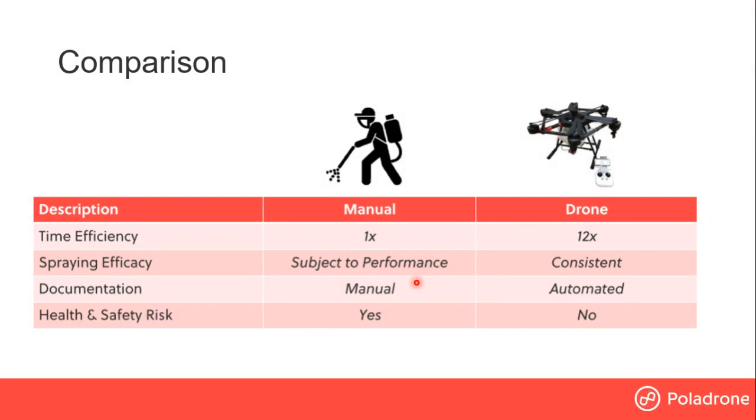Yeah, sure. But logically speaking, if we do spraying manually, of course in one day we can cover 1 to 2 hectares, depending on the environment also. But in terms of drones, our PV16S has been used and we have quite consistent data on that. One flight can cover up to 0.5 hectare, I would say, and in one day it can spray up to 12 hectares.